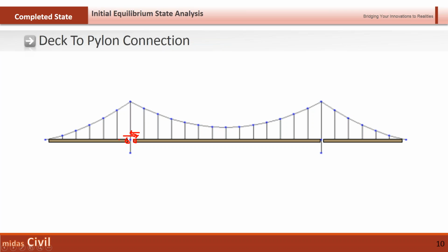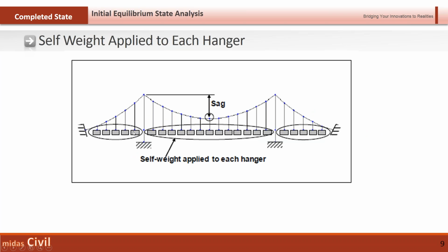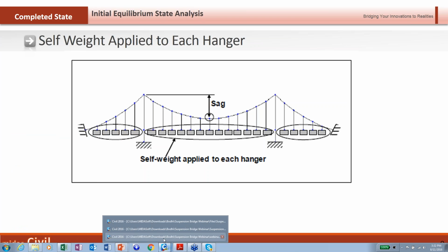Also, currently the model, because this is again a model to get the initial forces, we are just optimizing the model. So the point of interest will be to give loading in such a way. For such a type of loading, I have to simulate the deck connections in such a way that the deck portions will not be connected to each other. So I have to give the beam end releases in such a way for the deck elements also. Okay, so I will go back to the model.